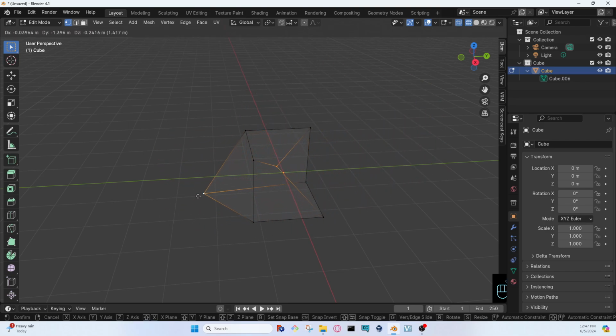Now, whatever you grab, if you grab the vertice, the distance between these two vertices that I have grabbed will never change in this mode because I have selected those two vertices and they had a fixed point between them. So let's just say they were 1.5 meters apart. They will stay 1.5 meters apart forever. When you have multiple selected, no matter how far I move them, they will stay that 1.5 meters apart.